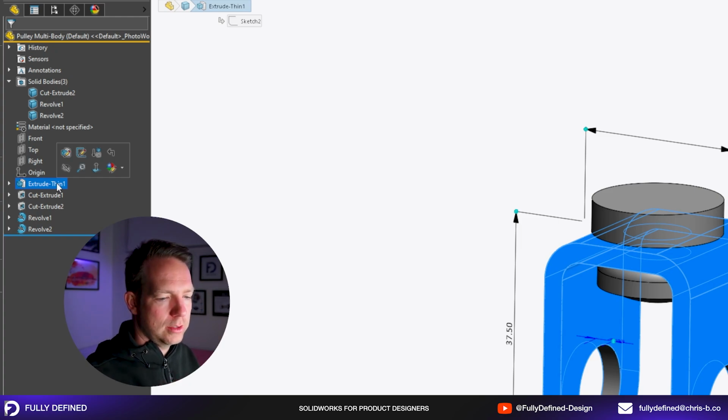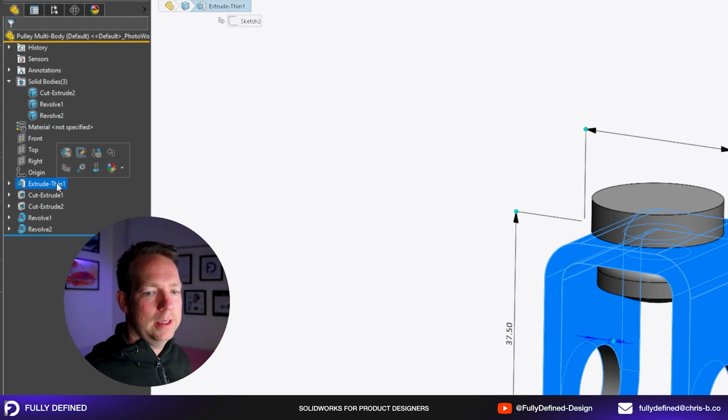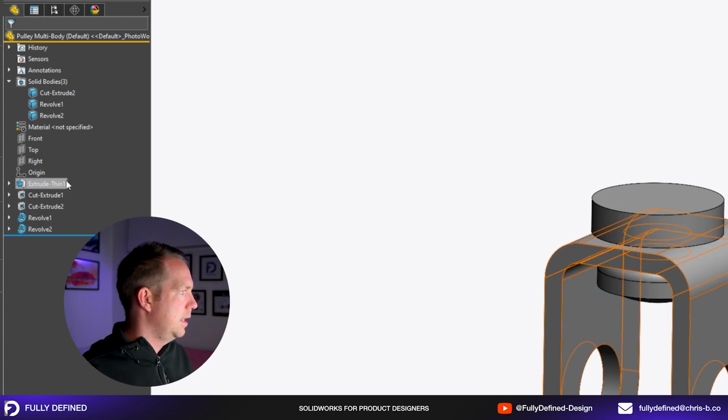The way that I do it in my current workflow is I will group a section of features to a certain area of geometry or a certain element of the design, and I will name them for that element or that geometry. Okay, not naming them for what part it is, because often my part files will have multiple features, geometry, elements, references from other parts that relate to lots of different things. So yeah, I'll show some examples later.